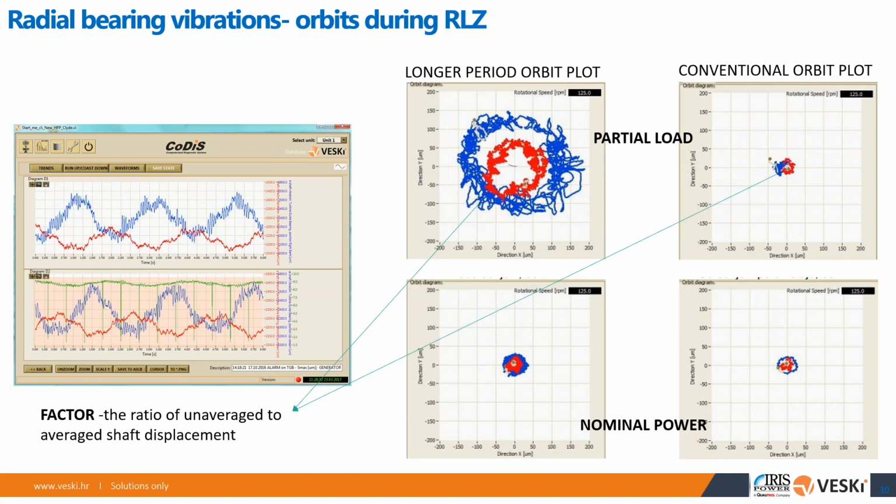Okay. Next question. When you come to a site, do you usually find a sufficient number of vibration sensors and configuration, or do you need to install additional accelerometers? We usually need to install additional accelerometers, in 95% of cases.